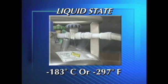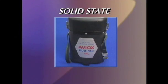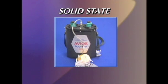Liquid oxygen is stored at extremely cold temperature, minus 183 degrees Celsius or minus 297 degrees Fahrenheit. As the liquid passes through warming coils, it converts to a gaseous state. A practical approach to the storage of oxygen is in a solid state form. Oxygen is generated by a chemical reaction process. The storing of oxygen in a solid state form is used in both general and commercial aviation.